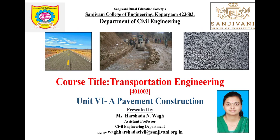So what are the requirements? How should the road pavement be? What are the requirements to have a good road pavement? Firstly, it should be cheap and easy to construct. It should be suitable for all types of traffic. It should not develop any corrugations, that is undulations. It should be strong and durable. It should provide good visibility at night.